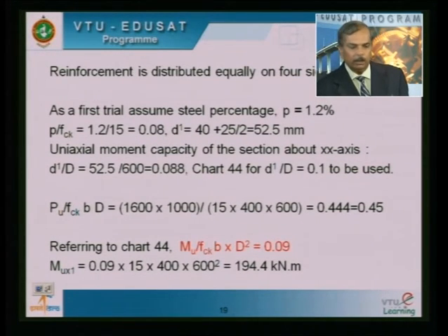So probably that is the reason why in most of the textbooks the effective cover is defined by taking the nominal cover to the ties rather than to the main reinforcement. Anyway, that is a small variation, so you need not worry much.